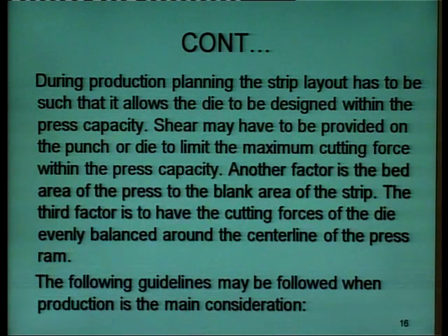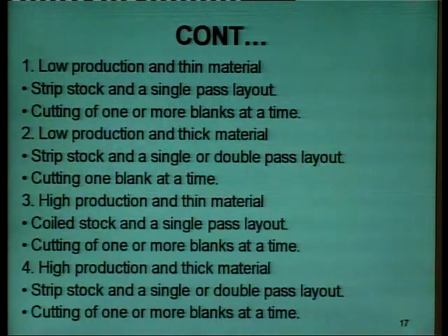Now, the following guidelines may be followed when production is the main consideration. When we are stressing production, the following are the guidelines. First, in case of low production and thin material, we will use strip stock and a single pass layout, that is, cutting off one or more blanks at only one time. Second, in case of low production and thick material, it is again strip stock and a single or double pass layout, meaning cutting one blank at a time.